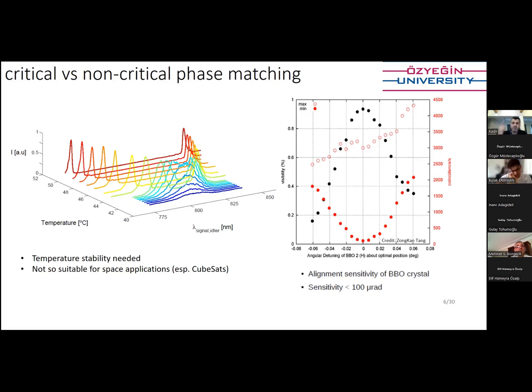There are some gases. But when you go to space, in the low Earth orbit, the pressure is around 10 to the minus 7 millibar, which means you have high vacuum. And there, you cannot use this method for controlling temperature using the thermoelectric cooler. What you need to do is dissipate the energy by using radiative dissipation, which means you need to make a big metal dish to radiate the energy, and it's not very efficient.